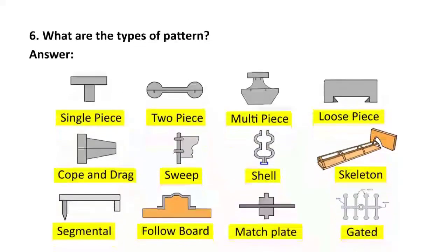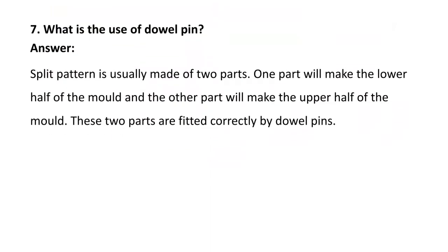So what is the use of that dowel pin? So split pattern is usually made up of two parts. One part will make the lower half of the mold and the other part will make the upper half of the mold. These two parts are fitted correctly with the help of dowel pins.